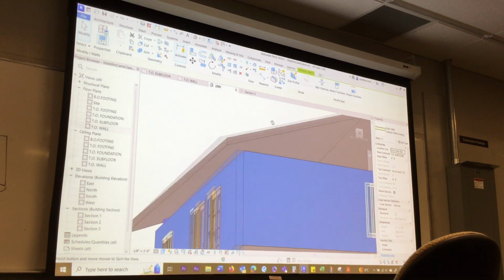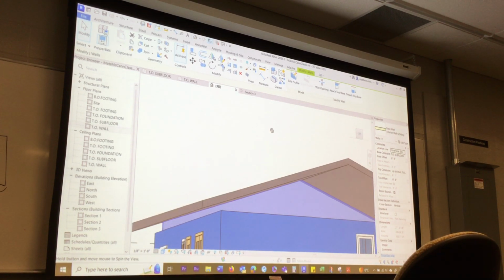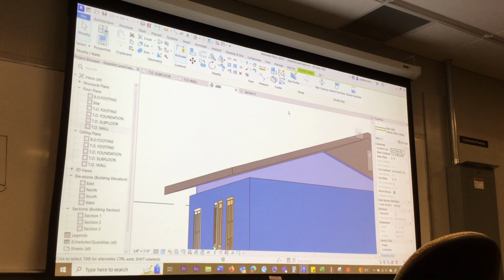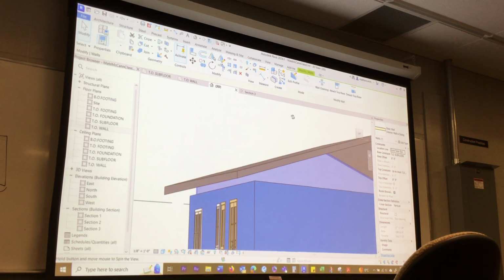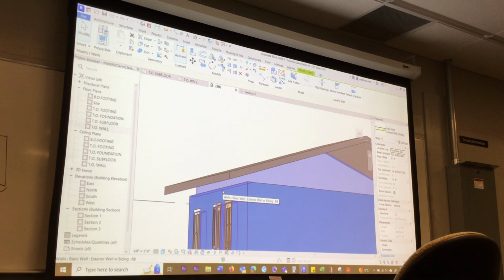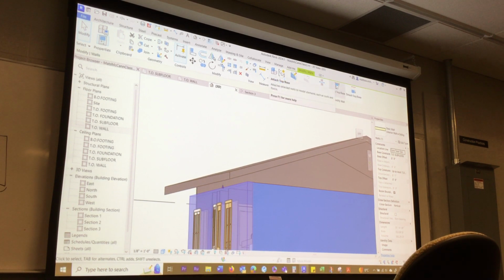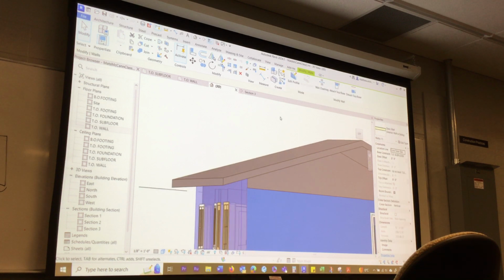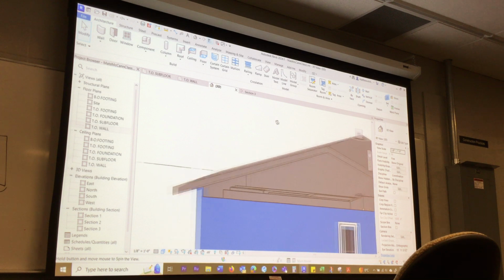This is where it gets tricky, and it's actually kind of fun. You zoom in. Working in 3D is always the best part. I want to pull this wall up because remember I wanted an 8-inch heel. Attach top/base. Click on roof. Ka-chow. Okay, no more draft in there.